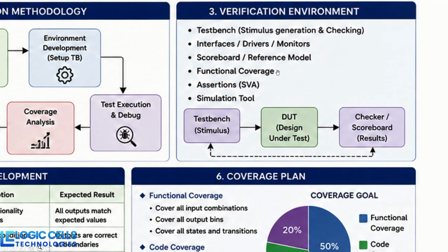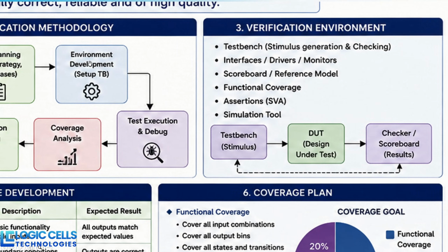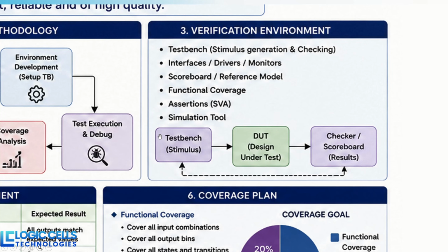What exactly is the verification environment here? I told you, you need to develop the test bench in the environment development stage. What will you develop exactly? I have shown one block diagram. See, this is your test bench block diagram. There is a test bench stimulus module. This is your data generator. For an adder, you need to provide A, B as inputs. Correct?